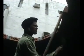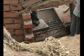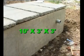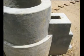Next to it, the sizes of the bricks are kept 3/4 at the top. For the closing of the dome, shuttering is done from inside and then the gas outlet pipe is fixed. After the construction of the biogas plant, the outlet tank is constructed. The size of the outlet tank is 10 feet by 3 feet by 3 feet. 2 outlet pipes are fixed in the outlet tank to drain out the excess slurry. Similarly, a circular inlet chamber is constructed to feed the biogas plant.